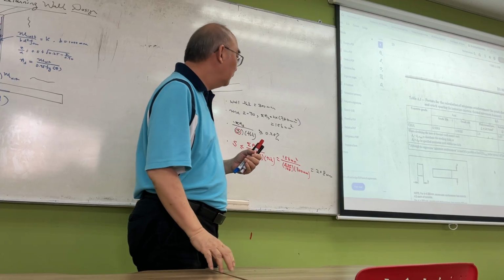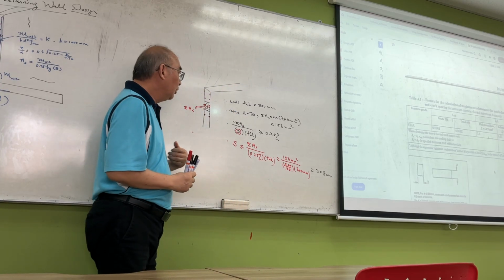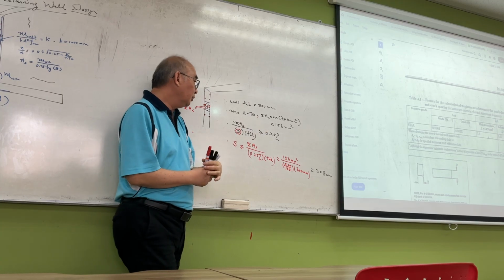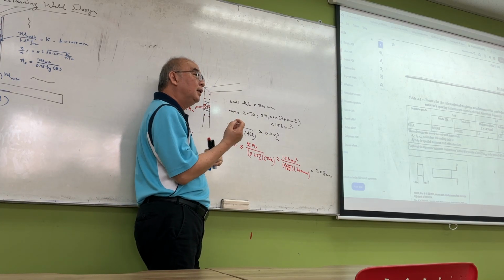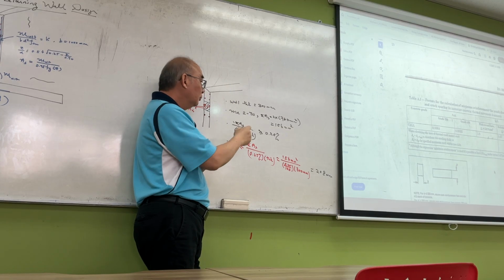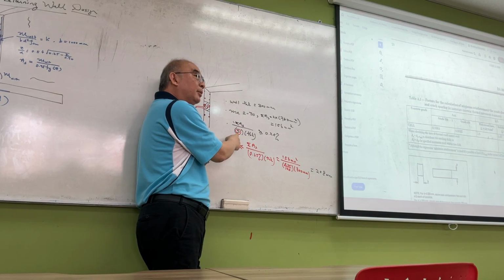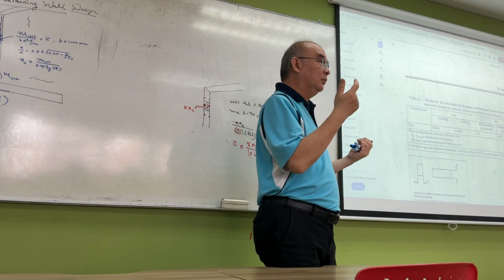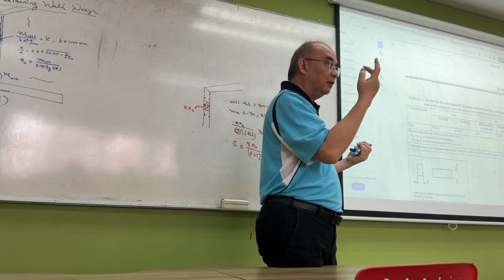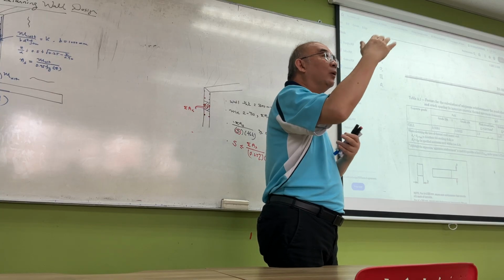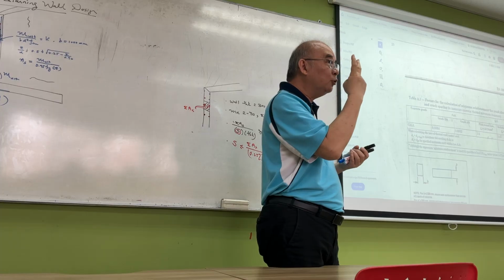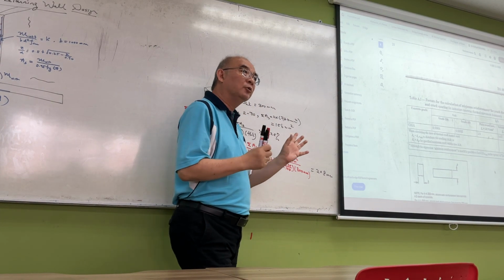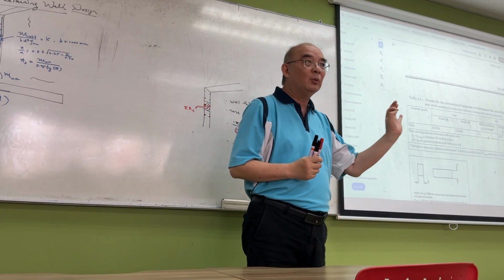Okay. Alright. Main thing is because we only have one equation. This is our design equation, right? In this design equation we have two unknown variables. One is summation of AS. The other one is the spacing. So before you design it, you have to basically choose what size of bar you use and what spacing. Right? So you have two variables, but you only have one equation. So how can you solve two variables in one equation? So you have to fix one of the variables first.